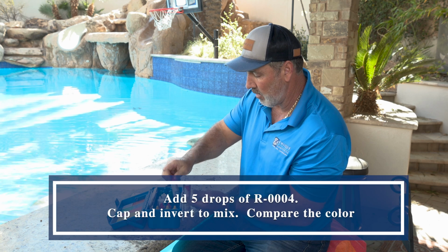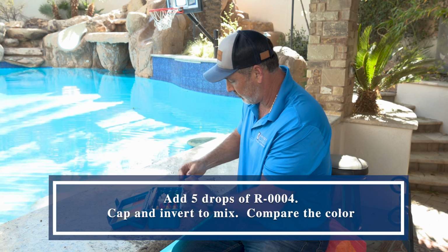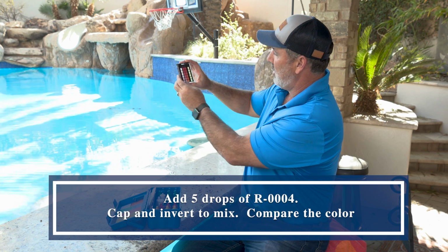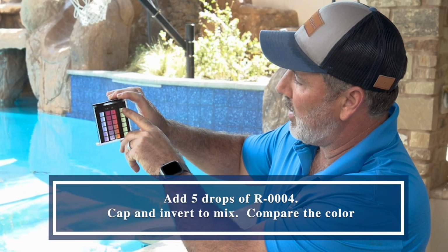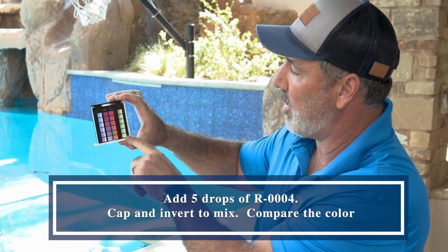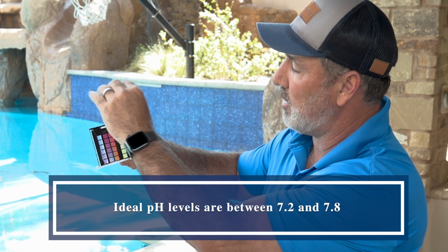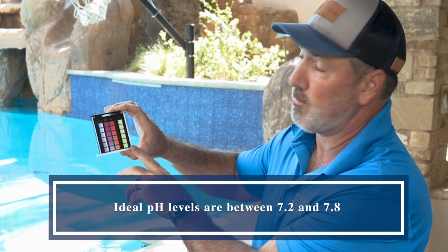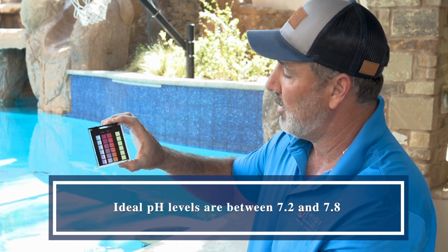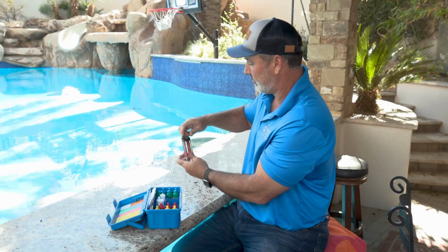So my reagent 4 is my pH reagent. Once you see any red or pink in this, that means your pH is probably 7.6, 7.8 or higher. The brighter red it is, the higher the pH. A lot of pools that we go to, we're gonna see really high pH. I have a pH management system on my pool, so my pool always stays around 7.2 or so. Right now it's reading somewhere around 7.2 based on the color.